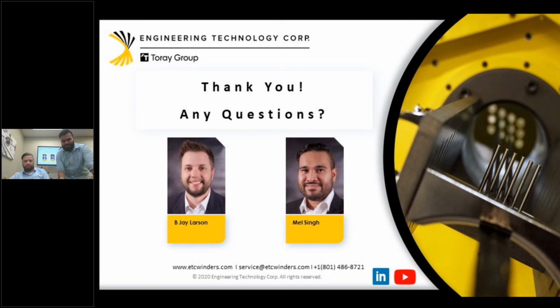Absolutely. Like I mentioned in the presentation, the position that FGX sits in is in between the FEA software and the filament winder. So anything that goes or comes out of FGX would then plug into your FEA software, whereby you would essentially determine how many layers you need, what angle these are, how many reinforcement layers, and so on, and then plug that information back into FiberGraFix. So you could easily verify whether or not a pattern adjustment would handle more pressure.